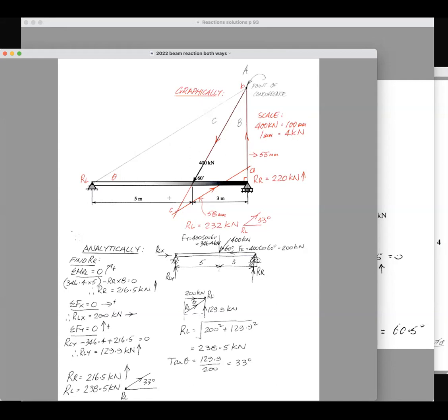We've got C there, so you transfer that angle down there using your set squares accurately, and then you draw that line up there. Now, where it hits the vertical force there, this force here will be CA, and where it hits that vertical force, that'll be A, and this force here, going up and down there, will be AB.